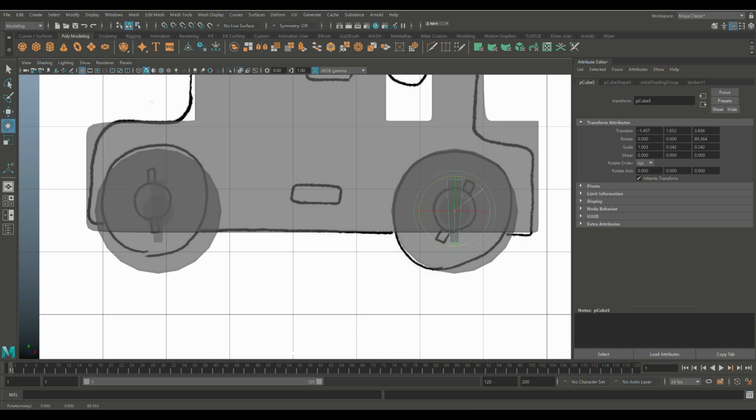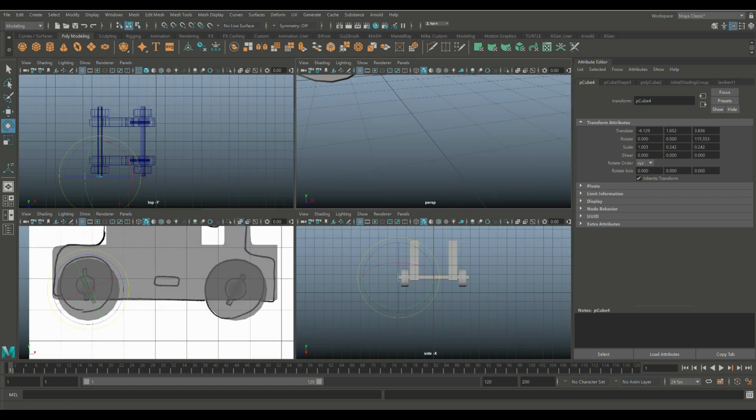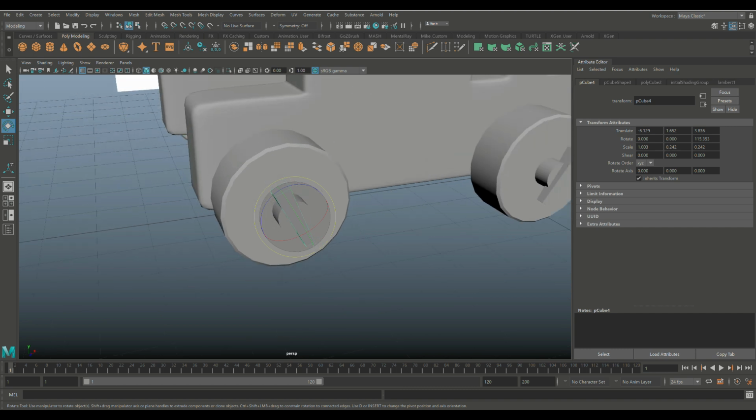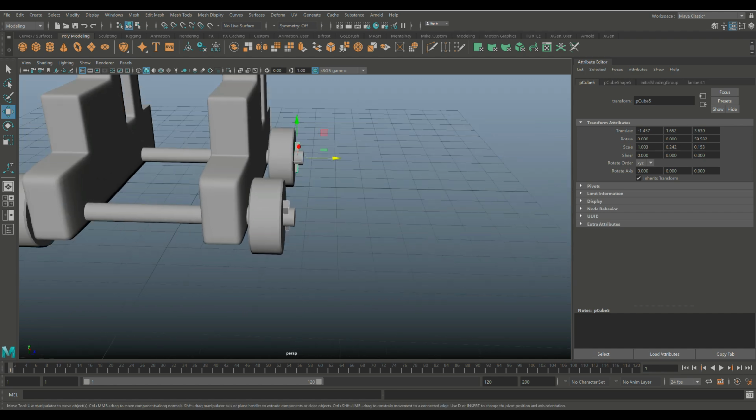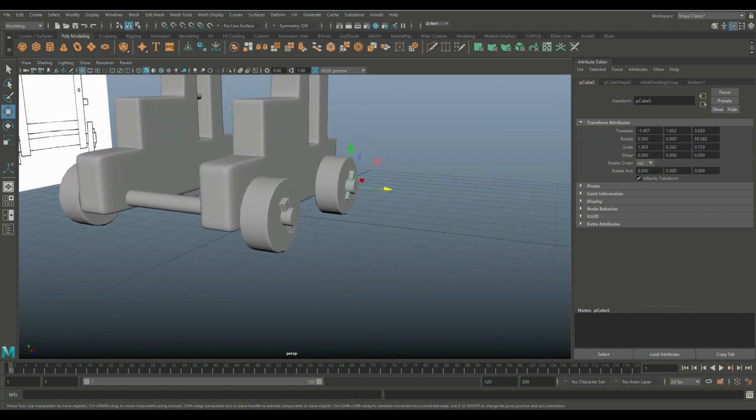Let's hit E and rotate this guy a little bit, and we'll take this one and rotate that one as well. And let's see how far in we are. Okay, so we got these two. W to move in, and we might want to make them a bit thinner, so hit R to push that in a little, W to push that in a bit further, like so. There you go. We're going to Control D to duplicate these guys, and move it over to the other end,